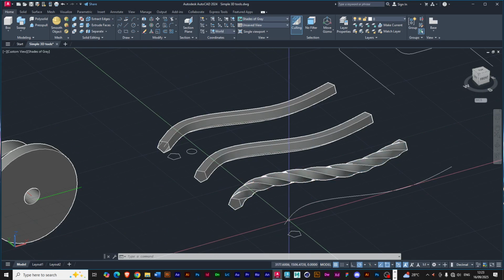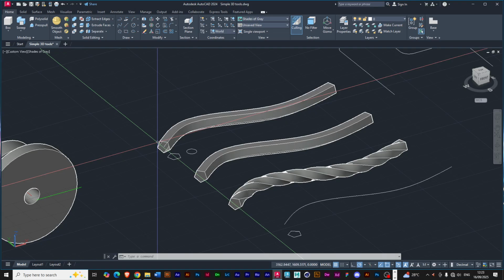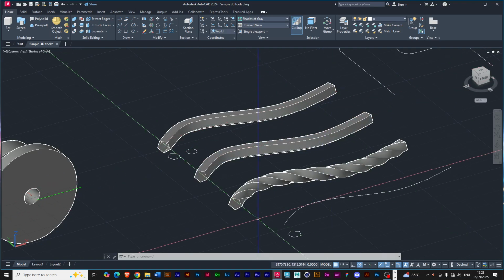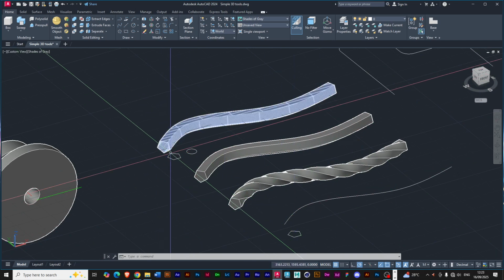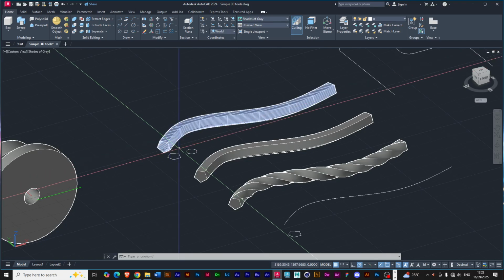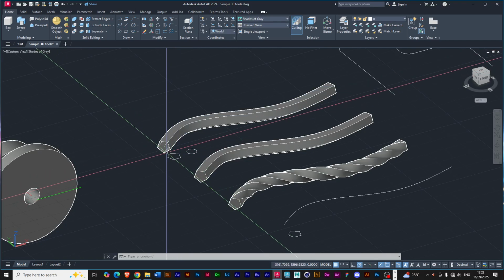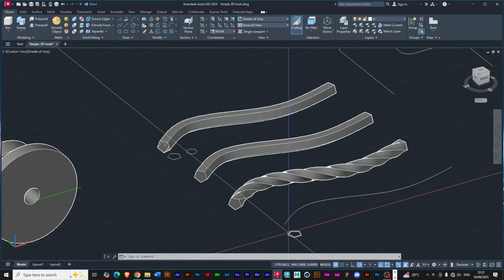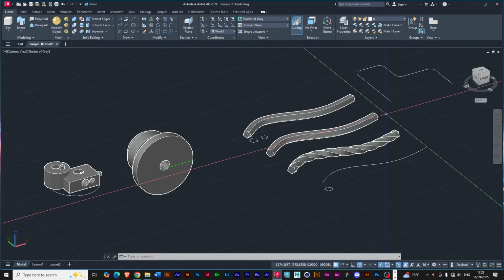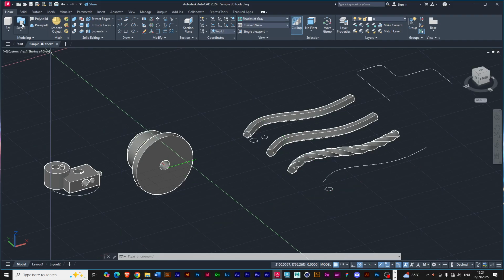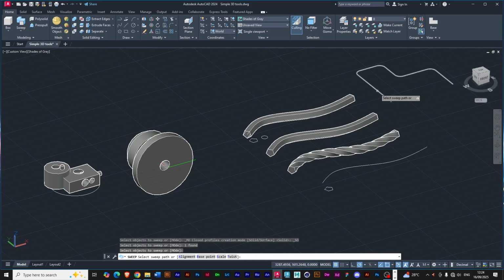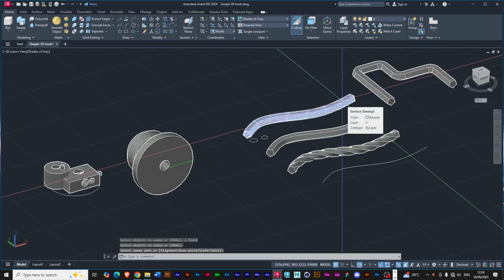So basically, that's the sweep. And one thing we should note is they don't need to be close together to work. You don't have to actually put it by the tip. You think, okay, it's working just because it's close. So what if I want to dip it on this? I can carry this and sweep along this. It doesn't need to be close. Important thing, AutoCAD did not say specify the distance. It just said pick the object. So if I carry this, I press enter and carry this, it will sweep along that one. It doesn't care about the distance.